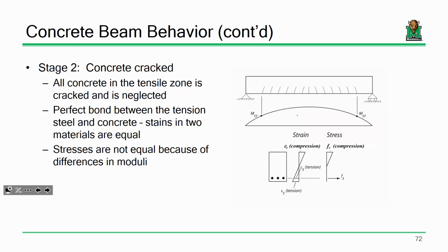Once that concrete is cracked, it's separated, and if I just pull on it, if the only thing that was concrete, it would be gone. Yeah, but it's not cracked as if parts there. Well, okay, what I'm getting at is that the concrete has lost the ability to resist those tensile stresses. But the other parts of the beam are still gripping onto the rebar, and the rebar is taking over. Does that kind of make sense?